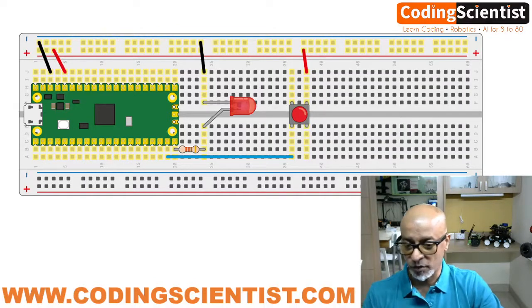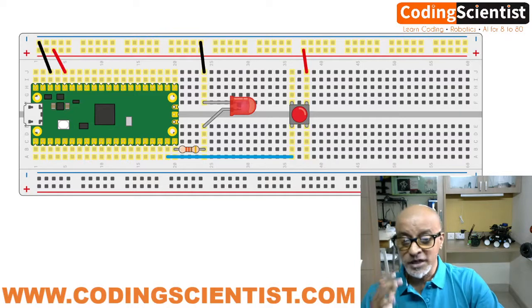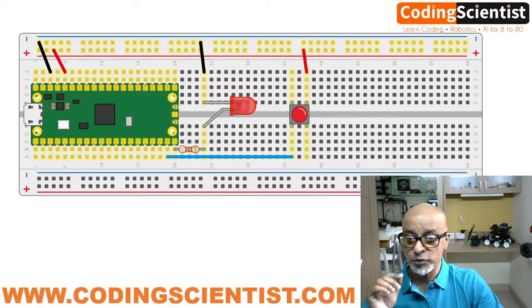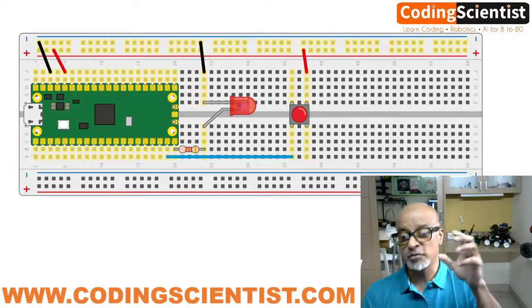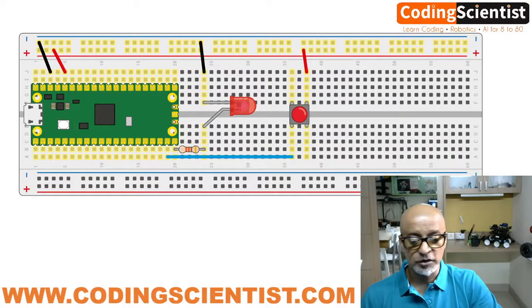This means when you set the pin, you need to tell MicroPython that it is an input pin and needs to be pulled down. That is how the pull up and pull down resistor functions when you add a push button to your MicroPython code. So let's open up our Thonny IDE and write some code for this.